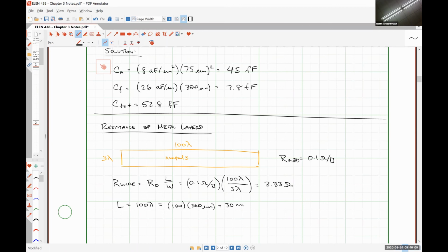So when you guys are doing your design portion of this class, you really need to think carefully about often using kind of wide, fat wires in order to minimize your ohmic losses between 2 different points in a circuit. That's going to help you with both heat dissipation and with minimizing the voltage losses in your system.